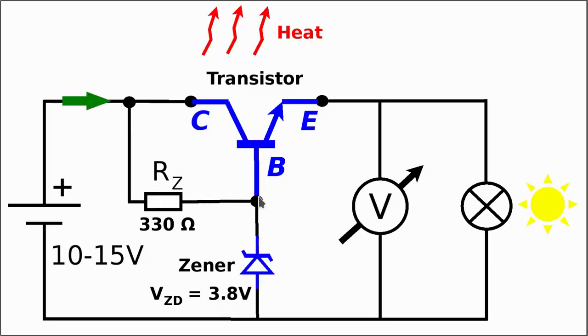So it means that we are one way or another monitoring the input voltage. So far so good. However, we have to keep in mind that the voltage we want to keep stable is the output voltage and not the input voltage, since the input voltage will change anyway. So we established that we have the output voltage here and we are not monitoring it at all. This of course means that we do not have any control over the output voltage, which is clearly no good. Therefore, we must put in some extra components at the output where we are monitoring the output voltage actively.